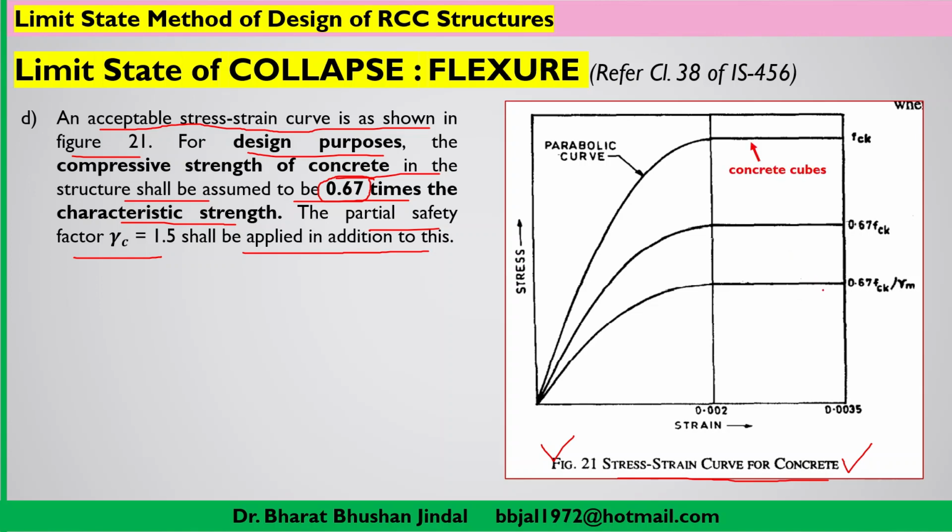See here, the very first curve is giving you the graph for characteristic compressive strength of concrete. This graph is basically the result of the testing of concrete cubes. That means when you are testing the concrete cubes in the laboratory, you may be getting this type of graph between stress and strain.